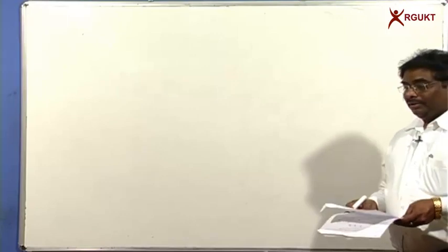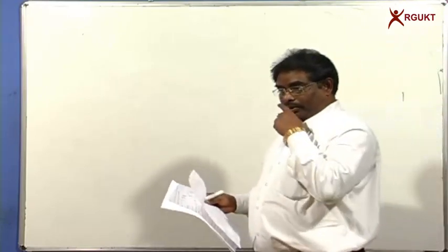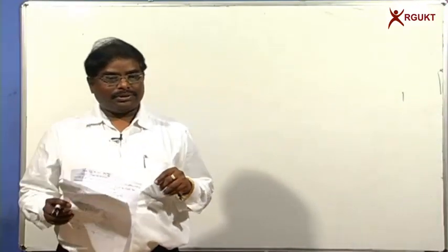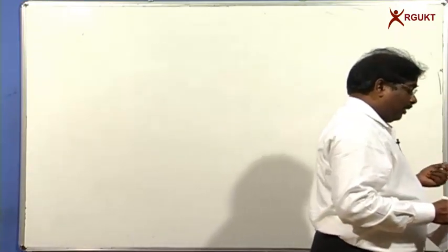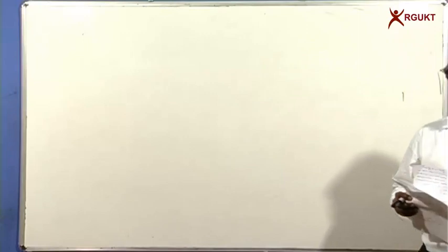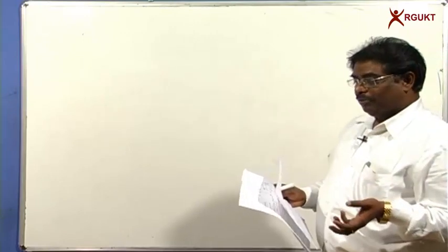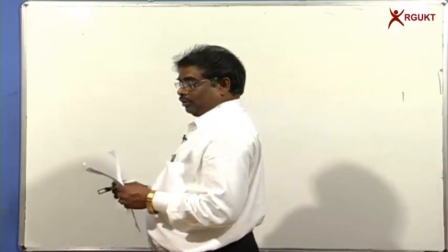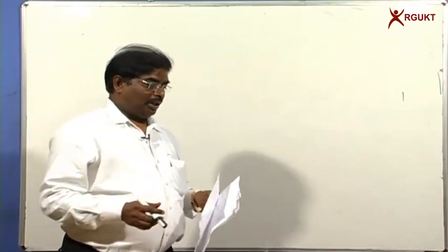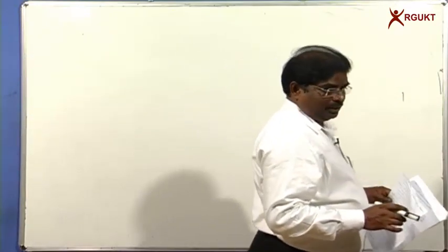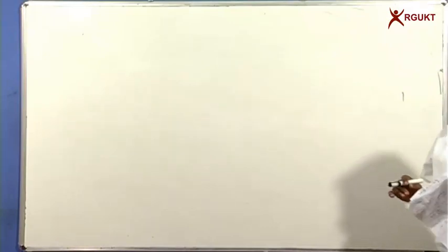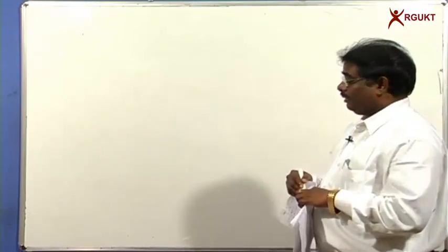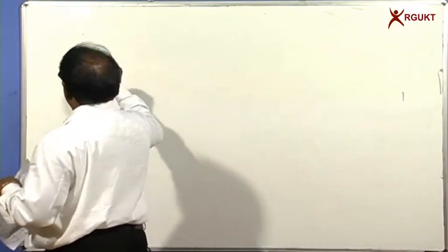For design purposes we are going to use the N-type flux, that is with respect to stationary coordinates, and the J-type flux will give you the capability of a species to move from one location to the other location. By this time you understand there is a relationship between the J-type flux and the concentration gradient, and one of the famous equations is known as Fick's law.